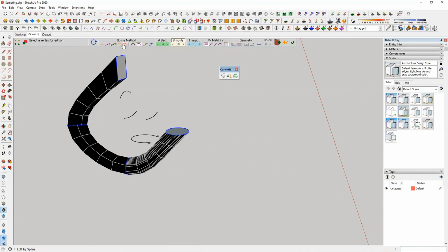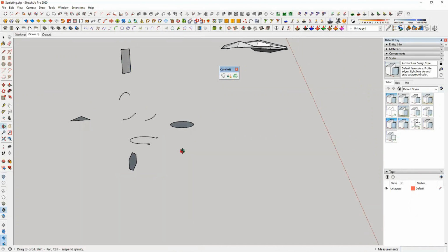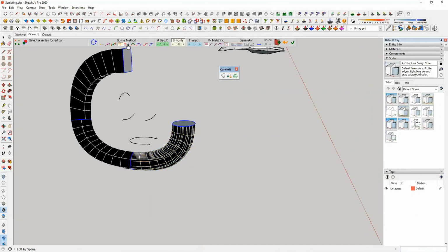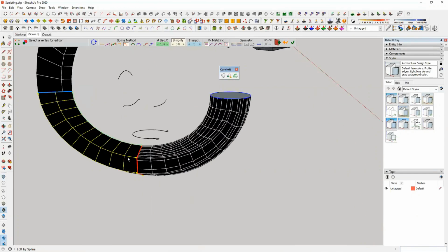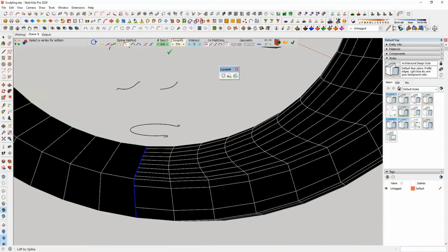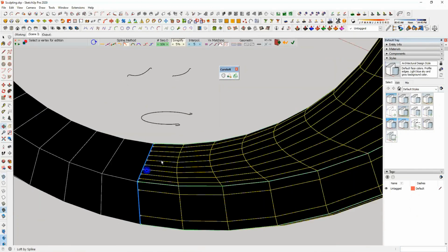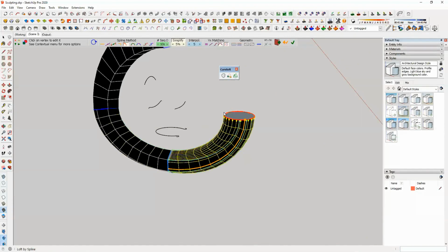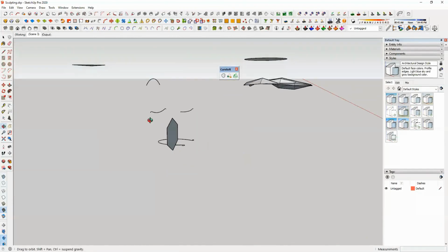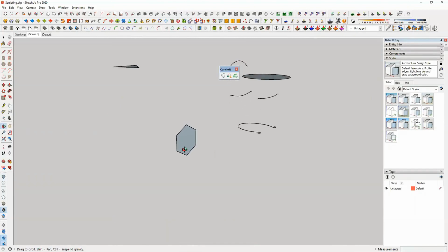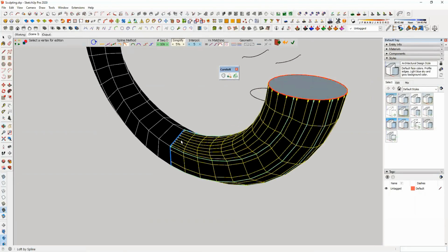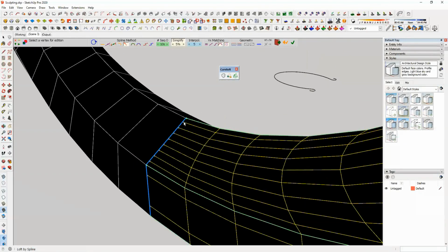And let's go again with the perpendicular option, where we have the curves a bit more perpendicular, and in this case you will be able to see the vertex matching in a much better way. Now as you can see, a circle and a hexagon will not have an equal number of vertices, right? So for that it will try to match the vertex from one point to the other.